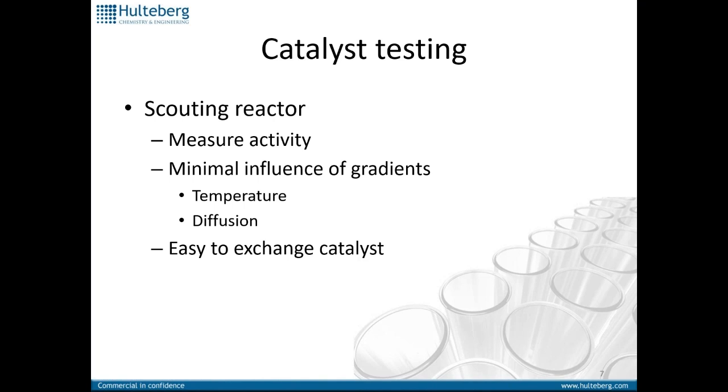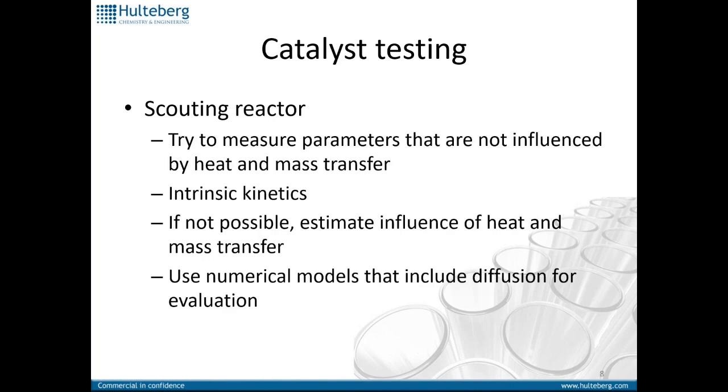In the scouting reactor, we are, as I said, trying to measure the parameters that are not influenced by heat and mass transfer. So we're actually interested in the intrinsic kinetics, the reaction that happens on the actual surface without limitations in moving reactants and products in and out of the catalyst or from the gas bulk to the catalyst surface. And this is highly desirable, but it might not always be possible.